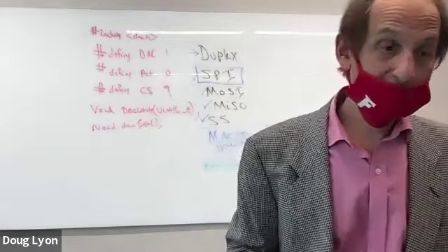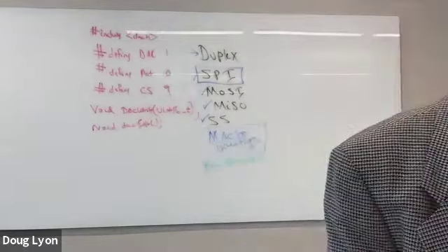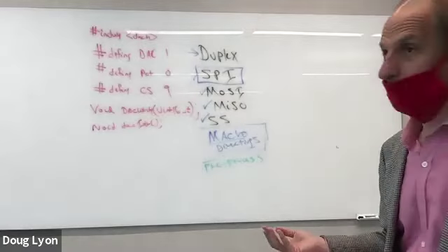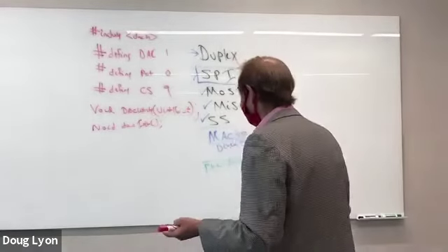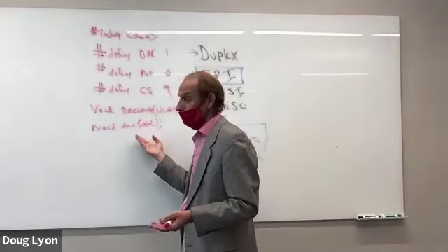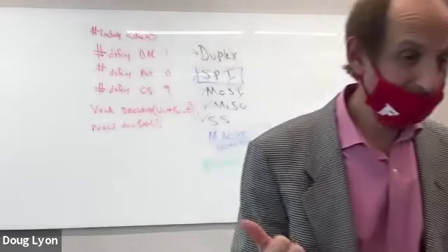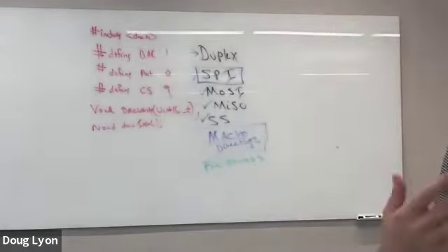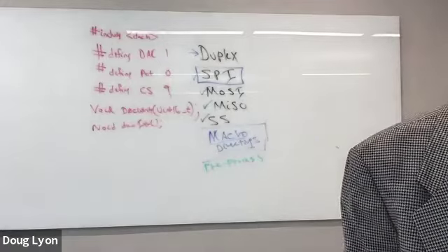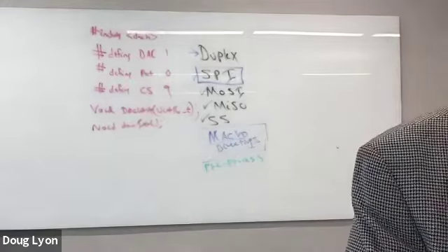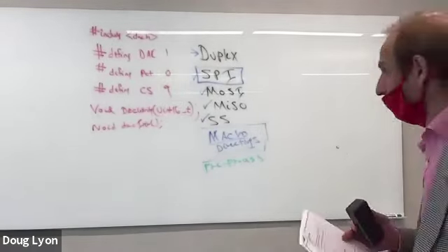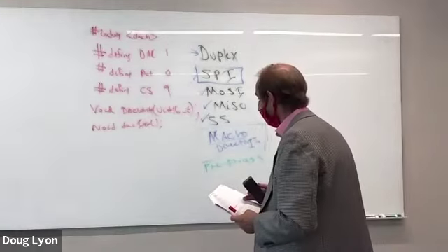Or else the compiler is going to look at that stuff and say, I don't know how to do a DAC write. How does that work? I don't know how to do a DAC init. I don't know how to do those things. But if you have it in the prototype, the compiler will say, oh, there's some sort of a subroutine I can link to, and I'm going to find the symbology for that in my linker, and it'll give me an address. I'll do a subroutine, a jump to subroutine.